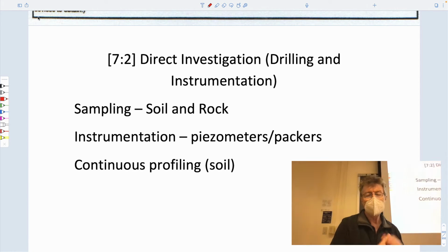Geophysics is just a way of using some proxy parameter that you can pick up remotely. So it would be seismic velocity, the dielectric properties of the soil measured by radar, or electrical properties of the soil, resistance, and use those as a proxy for the materials that are there to map out the stratigraphy. That would be the third part, which would be Thursday.